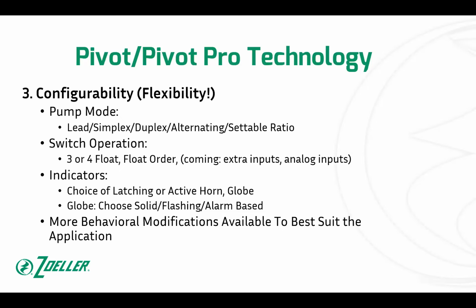Yeah, exactly. If you wanted a certain amount of water in the tank, you just wouldn't have your pump turn on until something above that, and you'd have your stop float turn off to retain that amount of water in the tank. So you're just pumping off the excess, I suppose. But yeah, there's no reason you couldn't set it up that way.